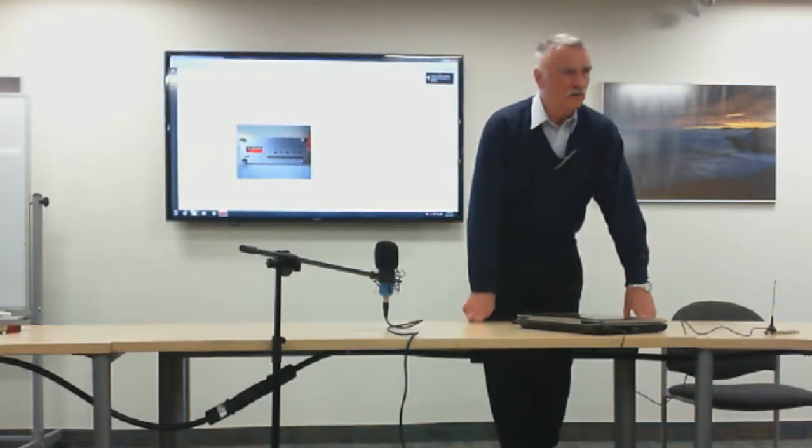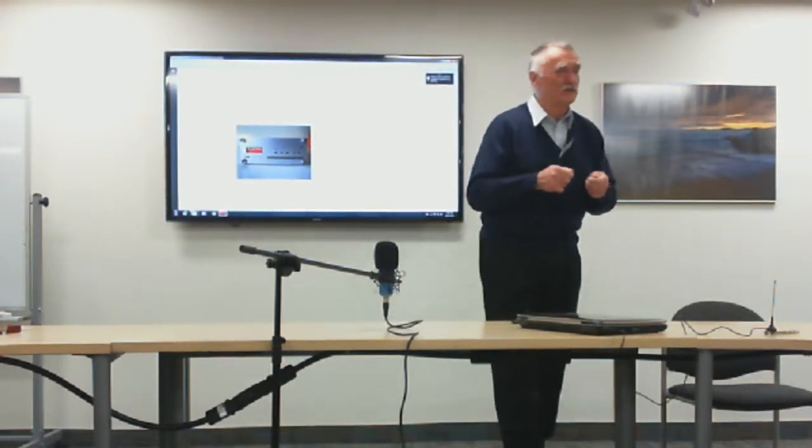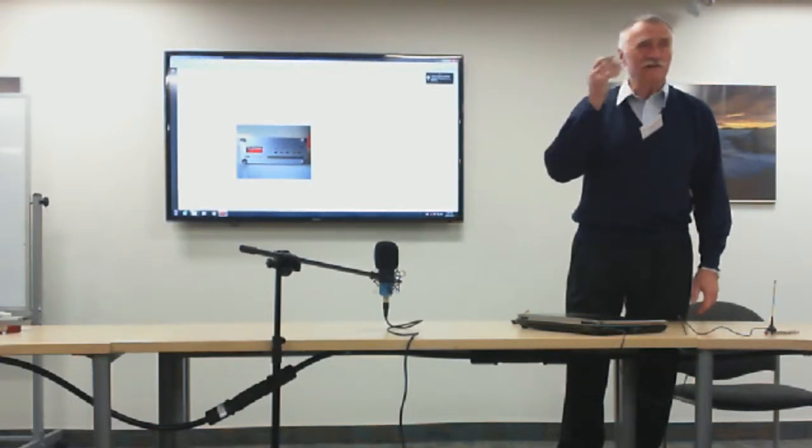And the modem is a modulator-demodulator. What the modem is doing, it would interpret the digital bits and would turn the digital bits into audible audio frequency tones. Those audible audio frequency tones, then they enter the microphone input of the radio, and from there it's being transmitted as if it was voice. Now one up, please.